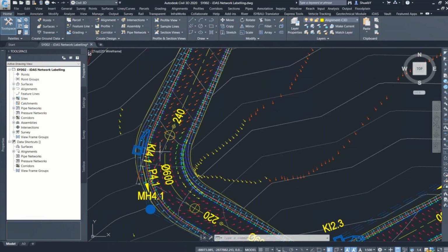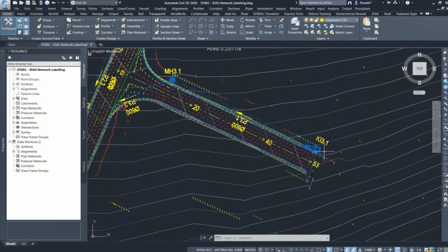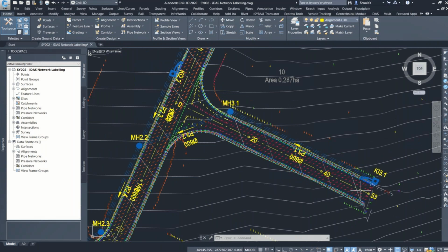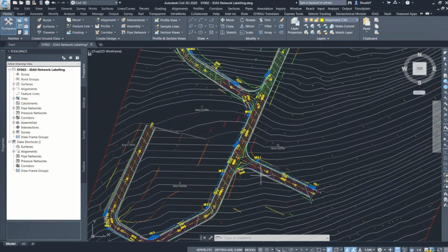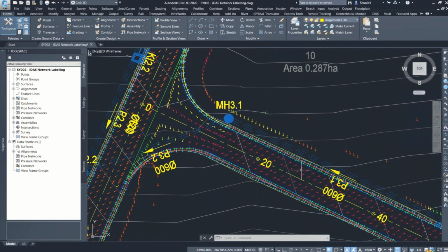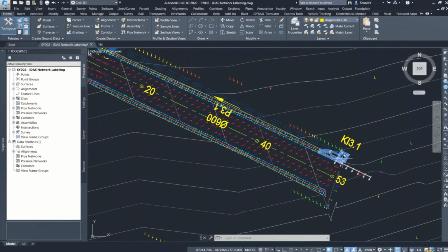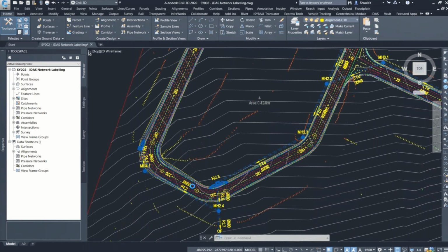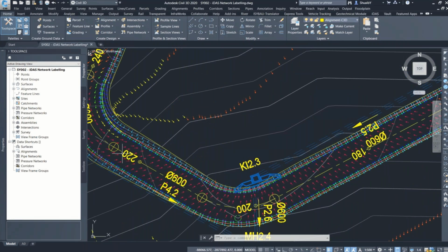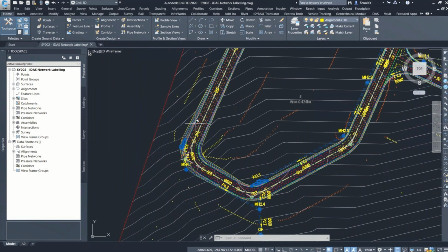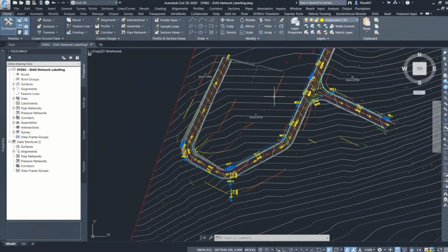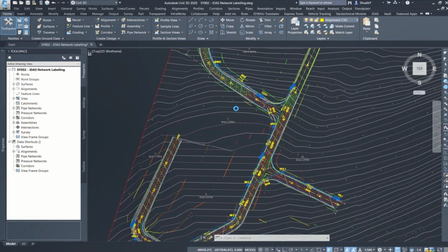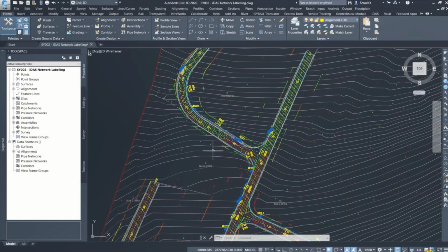And we've got the other branch that's starting from the top there, coming down. We've got this one here at the bottom, which is going to drain up into that and tap into network 2. So everything is draining down towards there. Again, you can see I've left the surface style on, so you can actually see how the road is designed to facilitate the stormwater design, which is very important. The road needs to be a contributing factor to the successful or proper design of a stormwater network.